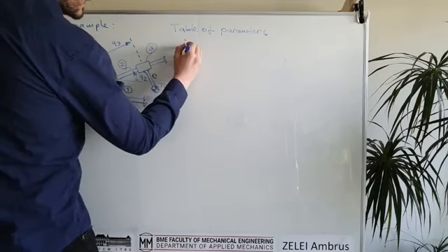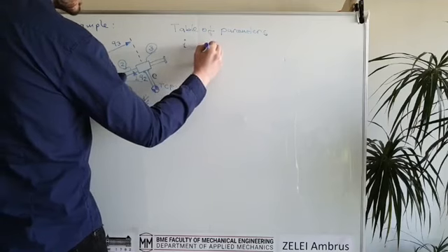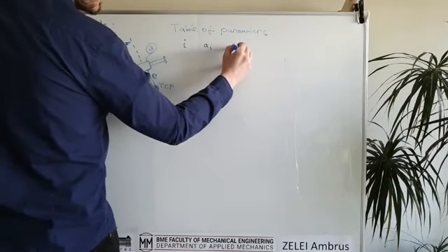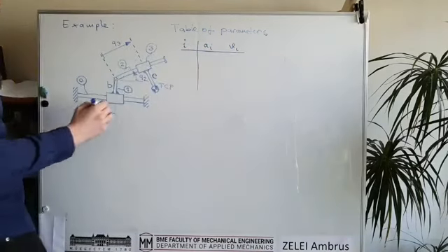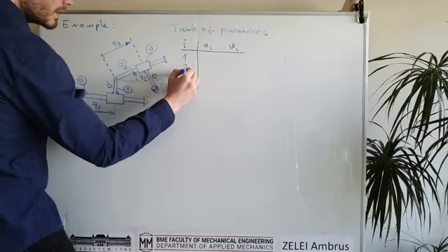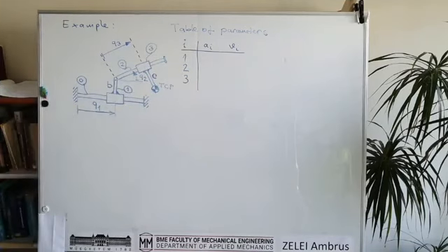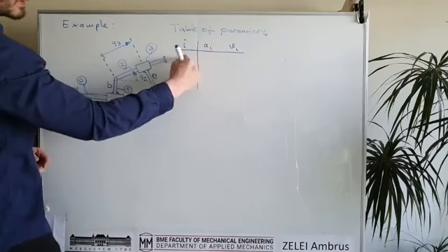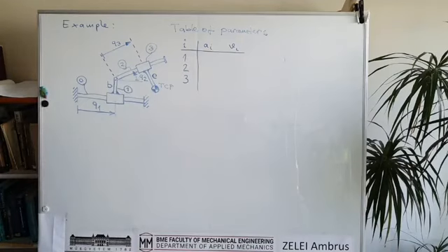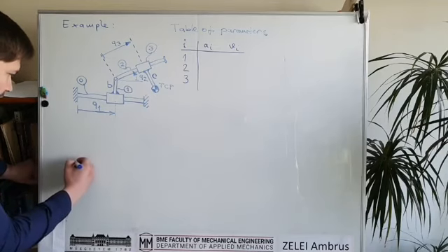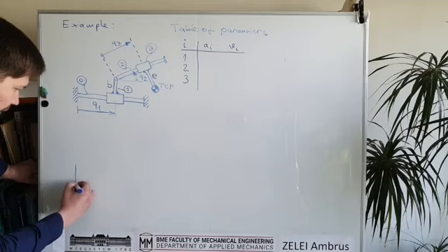this is the index of the link, and we will have the parameter for the translation and the other parameter for the rotation, and we can create this table nicely. So we have 3 links, and for each link we will need the transformation, which is given by 2 free parameters, as we discussed before. But if we want to do that, first we should introduce some coordinate systems, but I would like to do it in a separate figure, otherwise it will not really be visible.